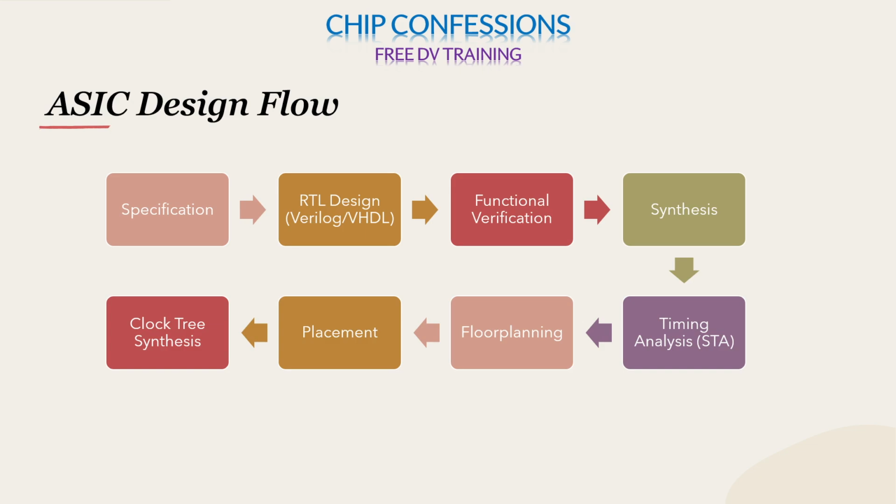Then we are going to CTS. CTS is nothing but clock tree synthesis. Once the placement and all is done, you should see whether that placement is proper or not, because we will be having a clock, and if we have flip-flops, like sequential blocks, that clock should reach all the flip-flops simultaneously. That is what your synchronous design is. That will be checked in CTS.